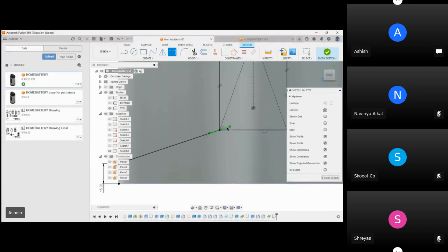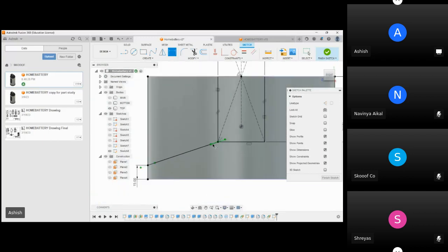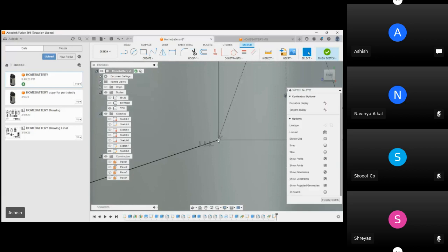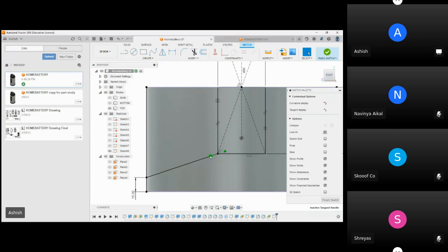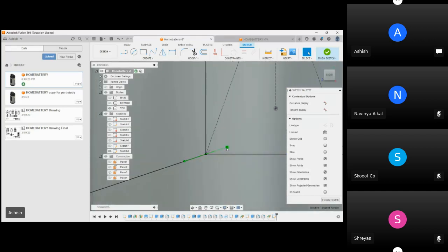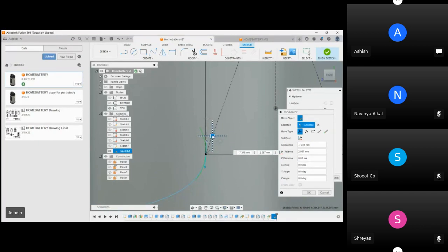Now you must move this line, right? You don't need a sharp edge here. So we will just select this point, then two points will be visible. I will press this point and press M on your keyboard. M means move; it is a shortcut to move. As you can see, direction and angle will appear. Just press this square and drag this like this. Once done, press enter.